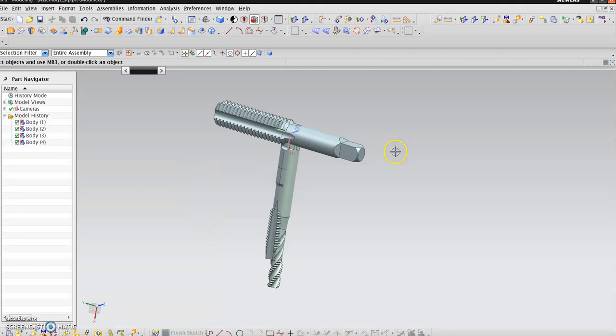For highly demanding applications where you need to machine Inconel, high strength steel, and high strength alloys, you need a phenomenal coating. The cutting tool needs to have enough fracture resistance, good surface hardness, excellent tool life, and at the same time provide fantastic lubricity in the cut.